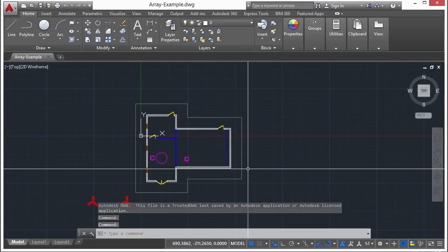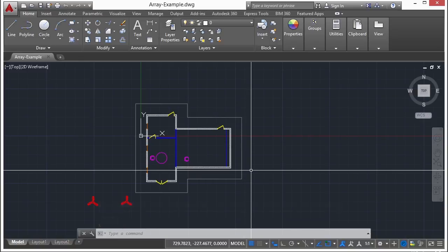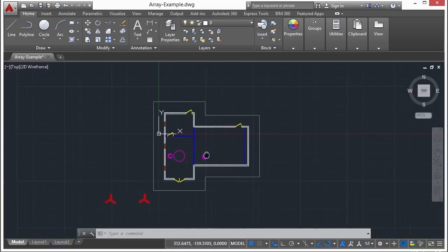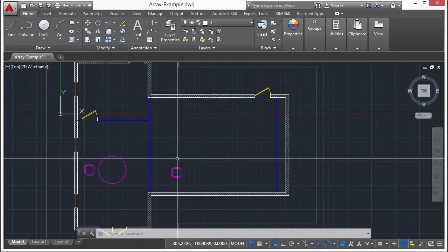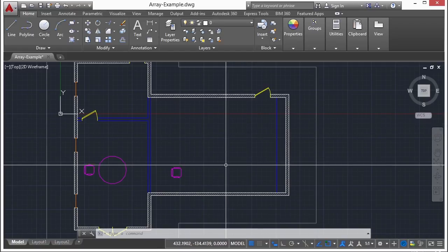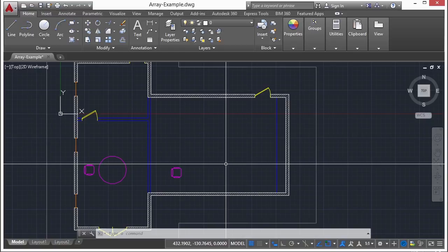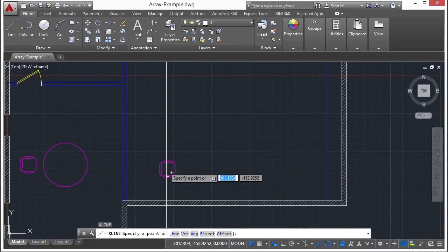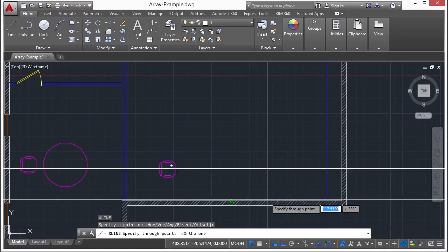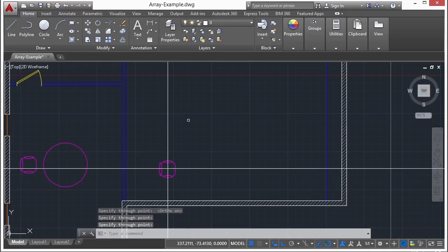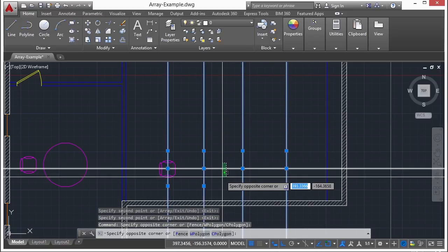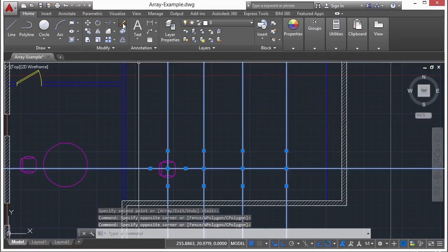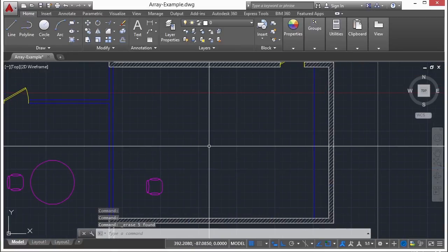In this example, we want to create a conference room display filled with chairs that are evenly spaced in rows and columns. So if we zoom in here, here's a chair that we have already drawn for us, and I want to fill it in with columns and rows of chairs. Now we could create construction lines. I could start off very quickly here, drawing some different lines, and then copying them over and over again, and I'd have to make sure they were right and correct, and I would do a lot of different work when I can get one command, the array command, to do all of that for me, and I don't have those extra lines in there.